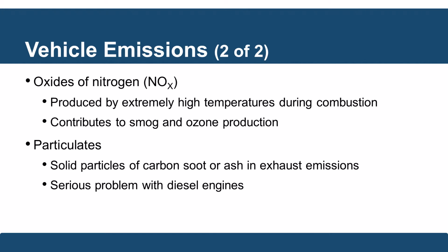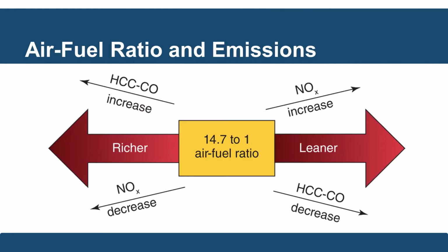In addition, we have oxides of nitrogen, or NOx as we call them. Those are produced by high temperatures during combustion, and that is probably one of the main contributors to the smog and ozone production that we've heard about. We also need to look at something called particulates. These are solid particulates of carbon. This is soot or ash, sometimes those plumes from diesels. And this creates problems in our atmosphere with how water bonds to those little particles.